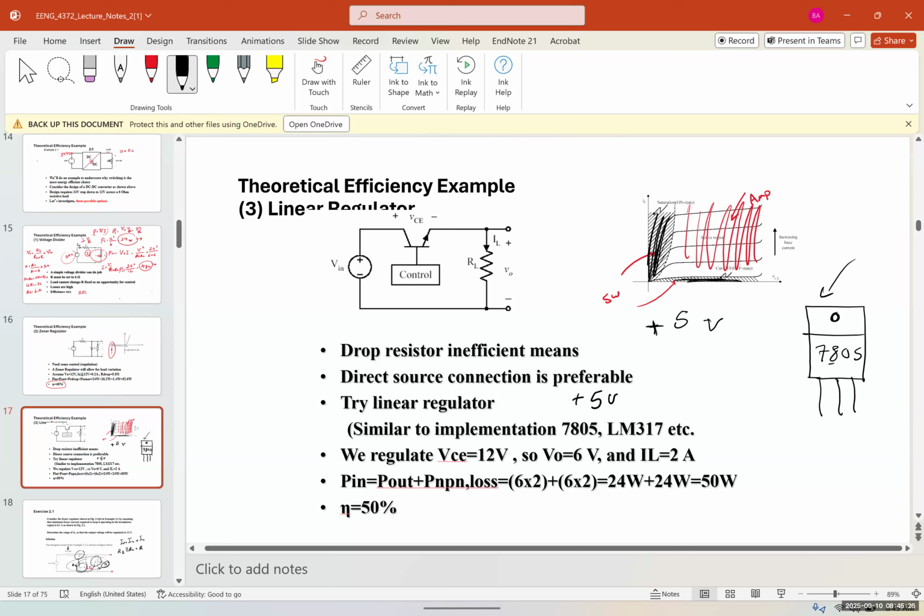Obviously, you have a range of inputs. You can't give it 200 volts in the input and expect to produce 5 volts. It's gonna immediately melt. And the reason that a voltage regulator has this heat sink at the back end is again because the efficiency is around 50% or so. You're gonna lose 50% of the power. Therefore, it's going to generate a lot of heat.